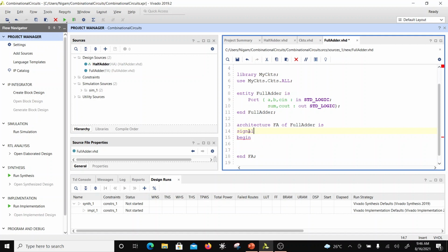And there may also be conflicts because one wire can have multiple drivers. In that case, you have to specify which one is a stronger signal than the other. We will talk about this in resolution functions later on. In case a wire is driven by two or more drivers, you have to have a resolution function, which we will discuss later on.